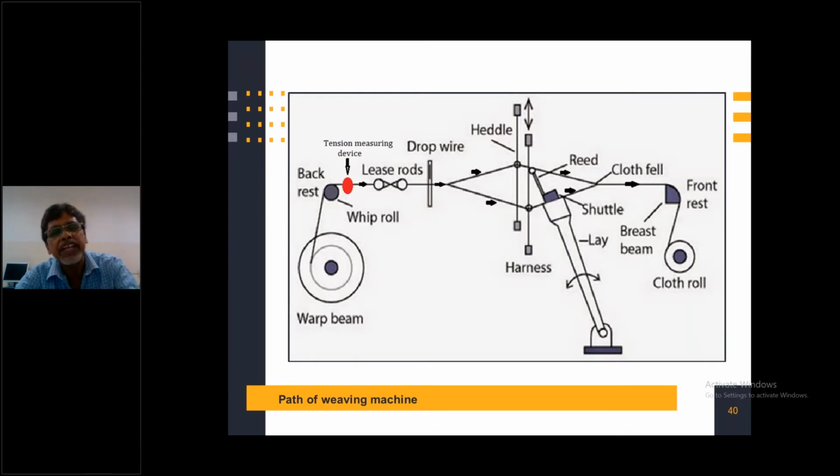So that's why the tension which we can see at the tension measuring device differs from the active area, where the geometry of the process is continuously changing through 360 degrees. From the mathematical model, we predicted that here the tension is 2.5 to 3.5 times higher than that of the stationary zone, which is indicated here.